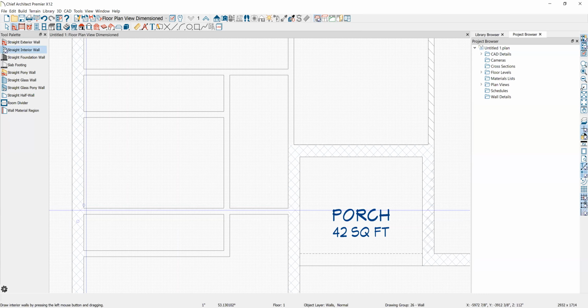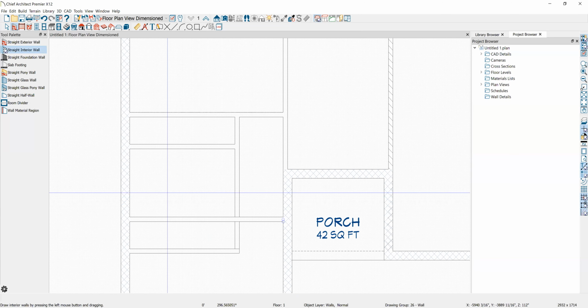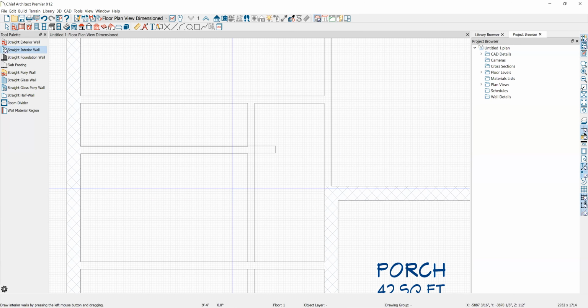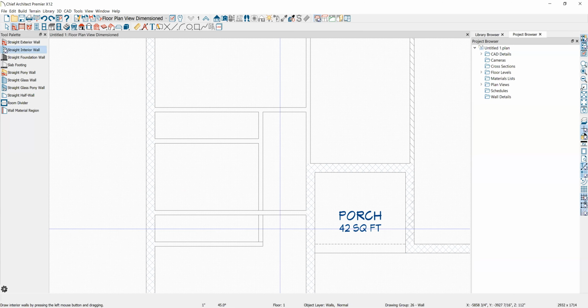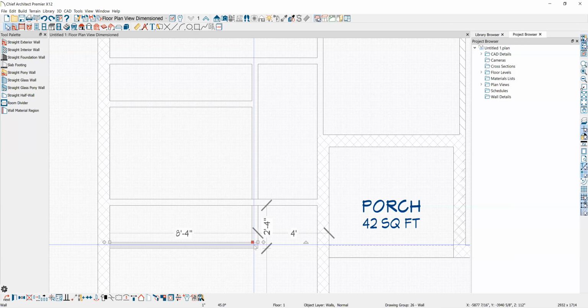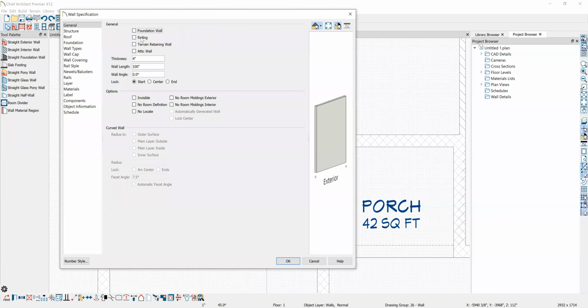Okay, looks like these we drag to the right. So in these we're going to drag everything to the right. Just get inside your lines, drag everything to the right. One thing you could do, because you can't actually tell what you've traced and what you haven't, is put a hatch on these walls temporarily. You can remove them later, so you can see what you've traced and what you haven't.